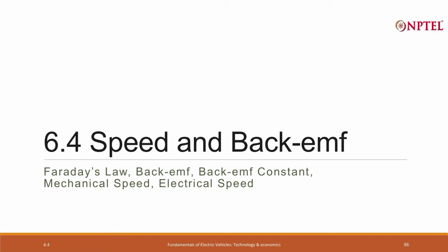So, what we just now discussed is what I have written here, and this equivalent circuit is very simple. The difference between the voltage and the back EMF is what will drive a current, and the drop, ohmic drop we call it, because it follows Ohm's law, I into R. The ohmic drop will be equal to the difference between the applied voltage and the back EMF. Is this clear? We are talking so far only about the PMDC motor. There will be an extra layer of complexity when we talk about the IPMSM. So far if there are any doubts, please feel free to ask me.